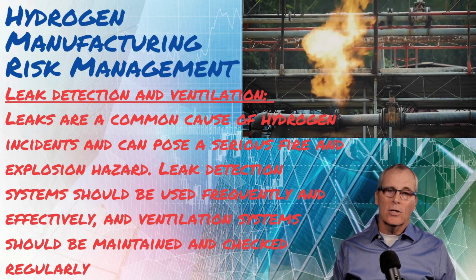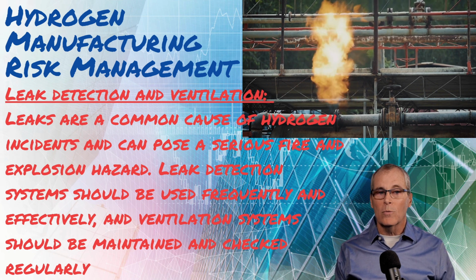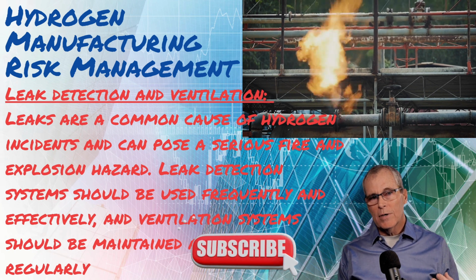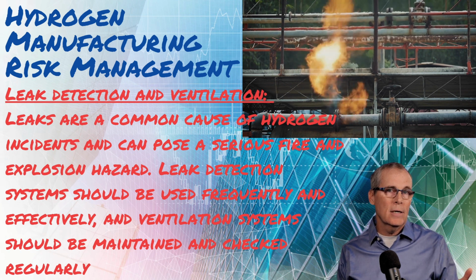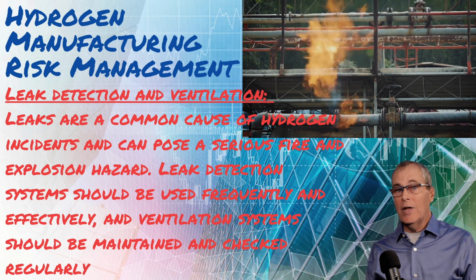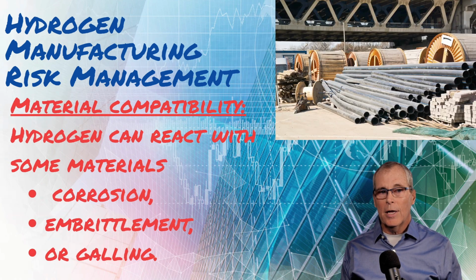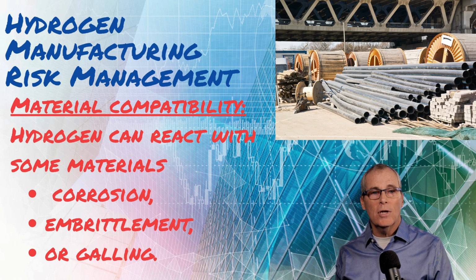Leak detection and ventilation could have stopped it if we had better leak detection, if it was maintained properly, if it was in service when it was necessary, if it was spaced right. You got to be careful with detection and ventilation, because if you have too much ventilation, you may not detect the gas, right? And if you don't have any detection, you won't know when to turn the ventilation on. So they have to work together, and it's a good option or opportunity for risk engineers to help.